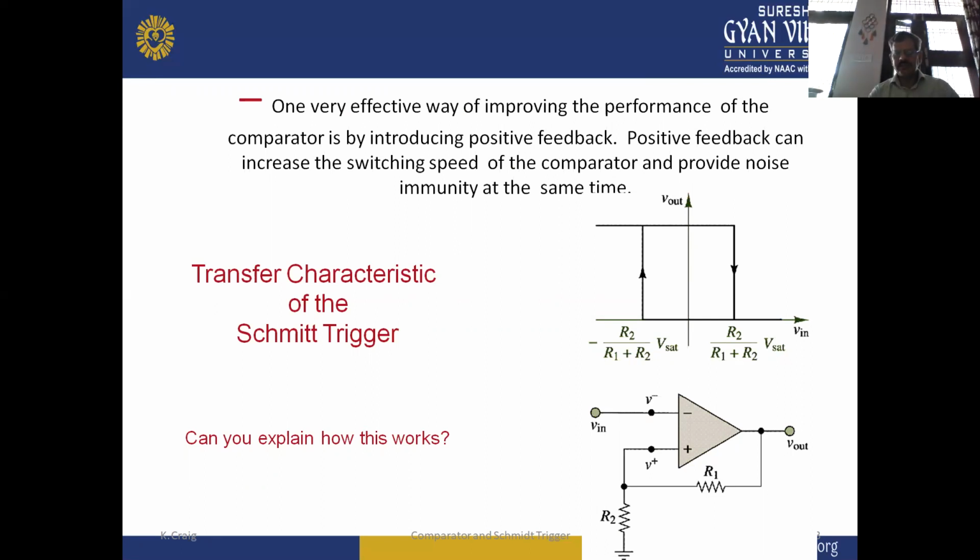in which the output voltage switches between minus R2 upon R1 plus R2 into V sat and R2 upon R1 plus R2 V sat.